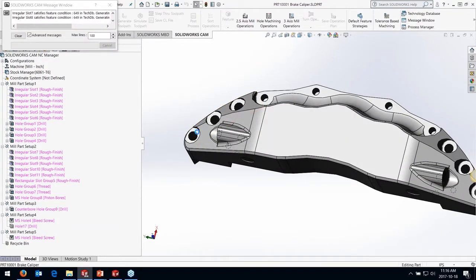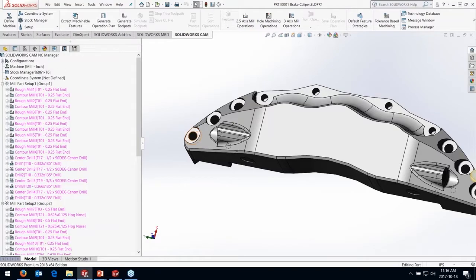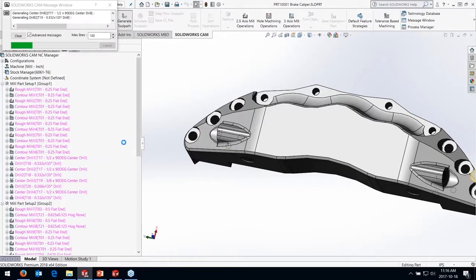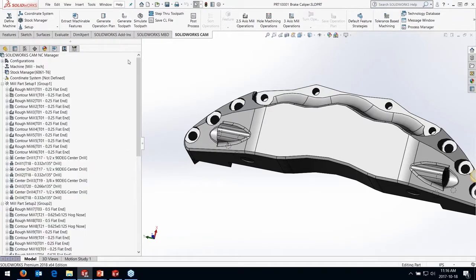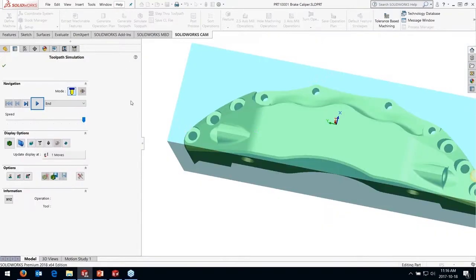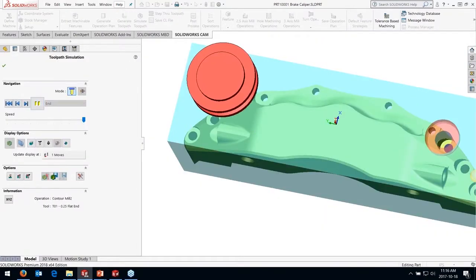Now, if I had to do this manually, I would have to go in and maybe put in a drill cycle, tell it the tool, tell it the settings, tell it if I want to peck drill it or just regular drill it, then put in a rough maybe to clear out a bunch of the material, then drill it, interpolate it and try and finish the wall, and then maybe come in and bore it.